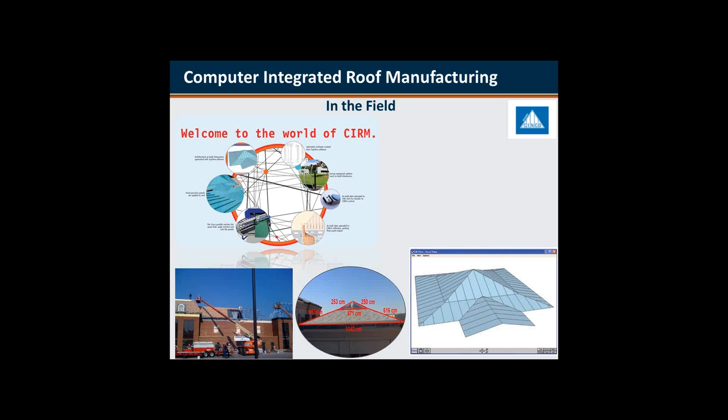This measurement process happens on these roofs about 3 to 4 times during this process that I'll walk you through. The process starts really with an architectural drawing, and this drawing is basically a blueprint that creates an estimation of what kind of panels they need to make. Well, that estimation that we call as drawn is never the same as the as-built dimensions when the actual roof goes up. There's a lot of things that contribute to that inaccuracy.